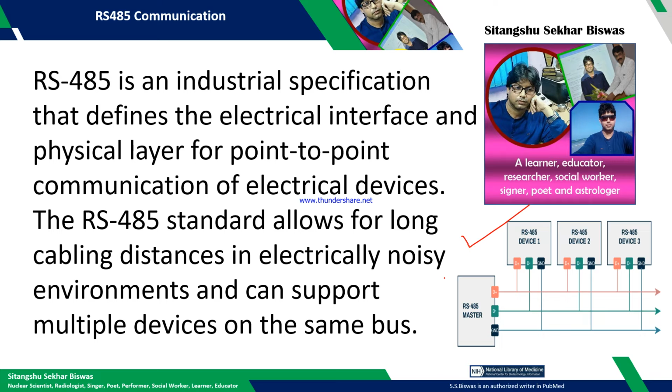So if you directly use the analog output from the sensor, then during transmission the noise can be mixed up and you may not be able to get the actual physical parameter reading. In such a case, if you convert the signal digitally locally at the sensor end, at the remote end, and transmit, it will be better. So for that purpose only this RS-485 standard evolved.